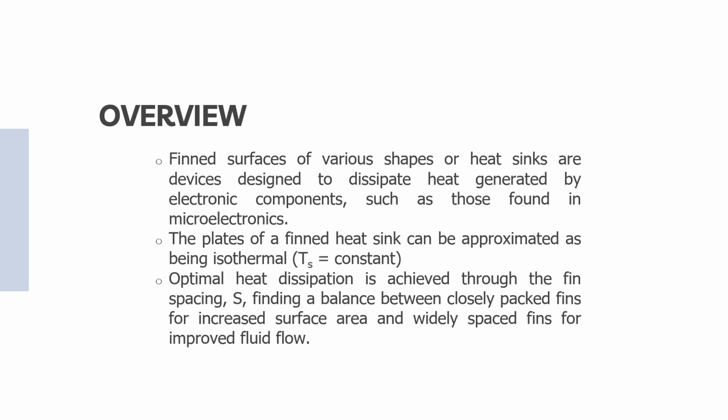The fin structure of the heat sink plays a crucial role in enhancing heat transfer. By increasing the surface area exposed to the surrounding fluid, fins allow for more efficient heat dissipation through natural convection. The design of the heat sink, including factors like fin spacing, fin geometry, and material properties, is important for optimizing its performance in removing heat from electronic components.